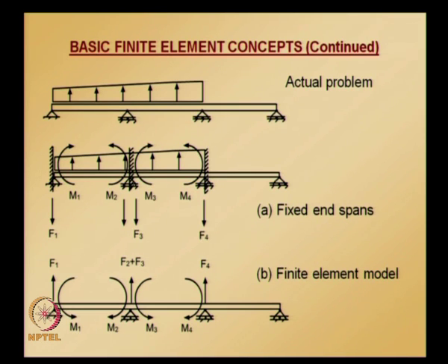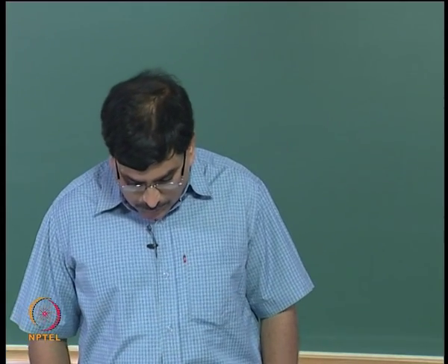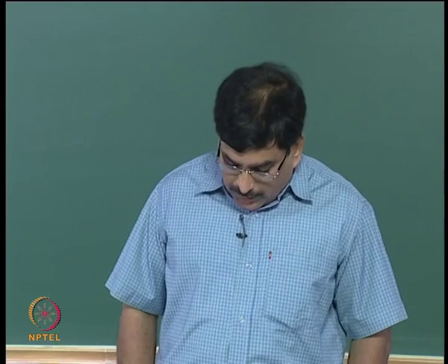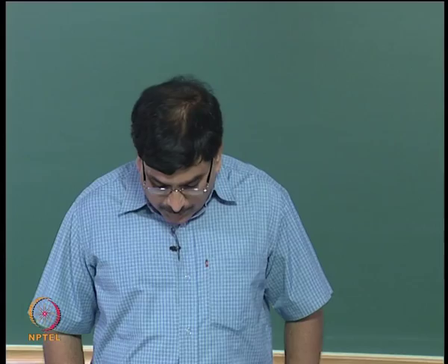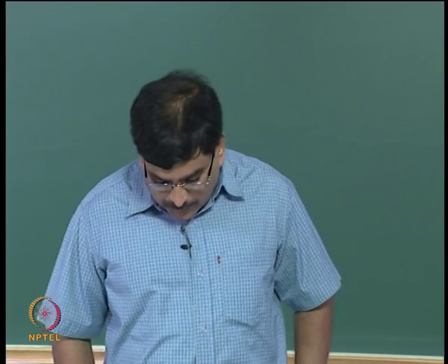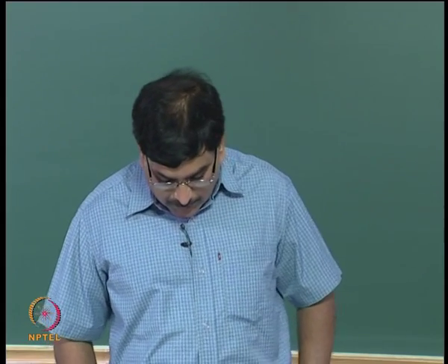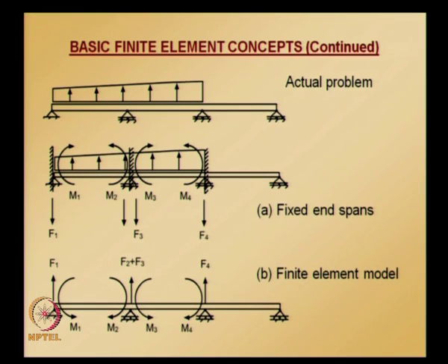Even though the superposition method is a two step process, for understanding purposes it affects only the final computation of the element solutions after obtaining the nodal values, which we can obtain in the usual manner. So you can proceed in the usual manner of writing element equations, assembling them and solving for the nodal unknowns. When computing element quantities, the exact solution of the fixed end problem is added to the finite element solution.